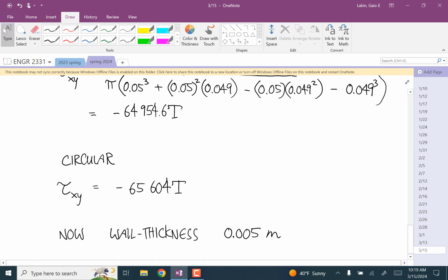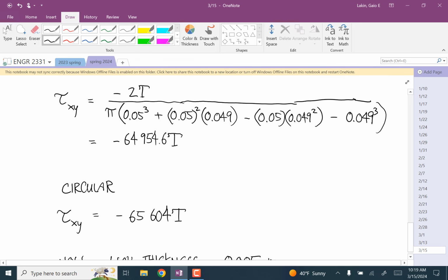One thing about this is at the outer wall, okay? If you're using the thin-walled tube approximation, what would you get for calculating the stress at the inner wall? This is a trick question. You get the exact same thing. We don't make any distinction as you go through the wall thickness. But technically it should be a little lower.